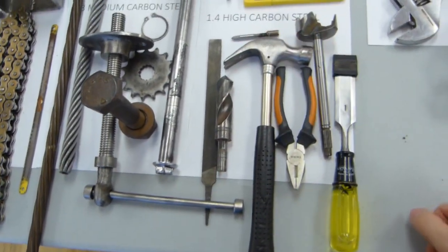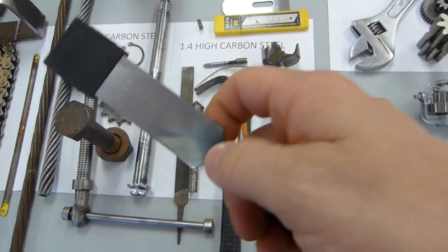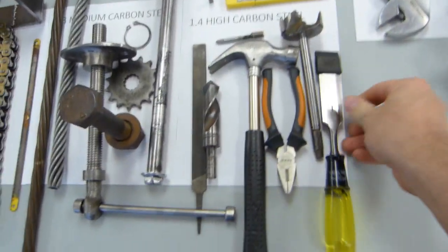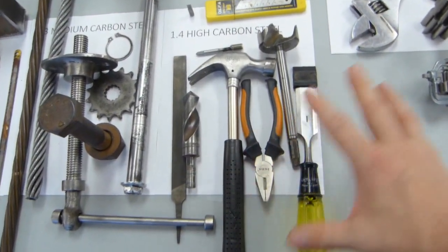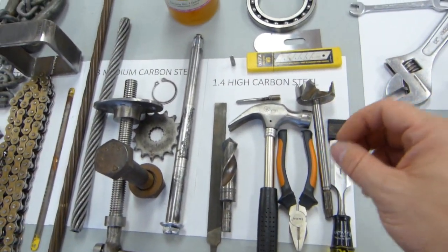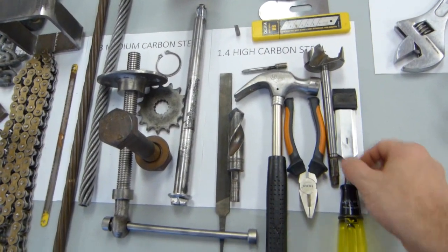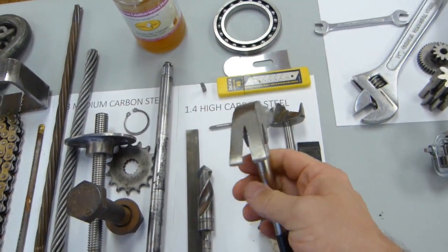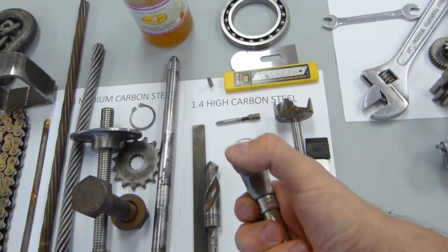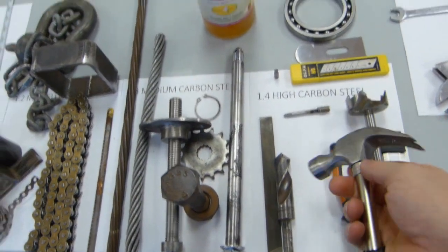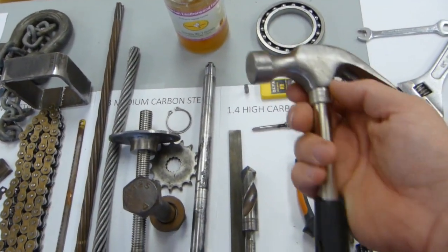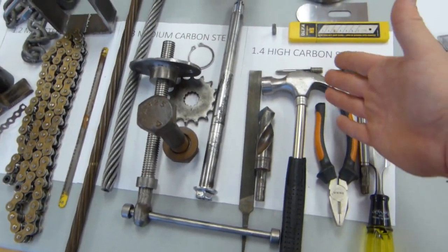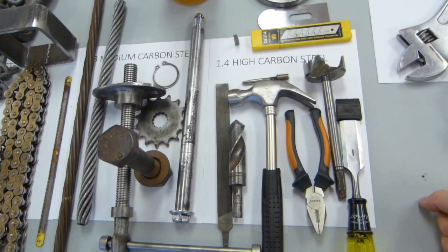This group is not really readily weldable. Think about it. Can you drill a hole into a chisel just so you can hang it on a nail? No. It's not happening. If you tried it, it's not going to work, because the drill bits are not significantly harder than high carbon steels. So these are very hard steels. You're pounding nails with a hammer such as this, and the face of the hammer does not deform. The nails deform, the nails bend repeatedly, but the hammer doesn't change its shape. So you cannot successfully weld hardened items such as these.